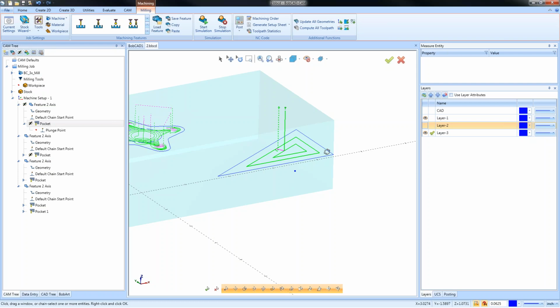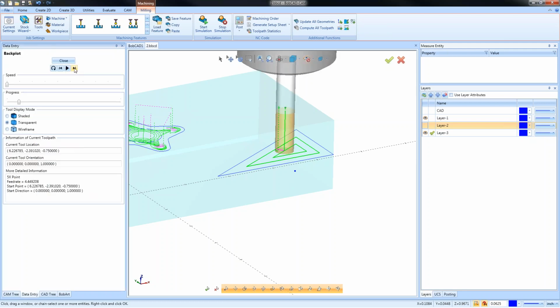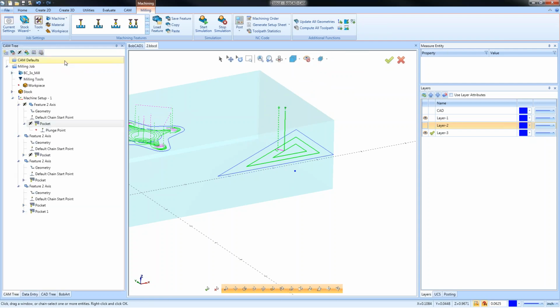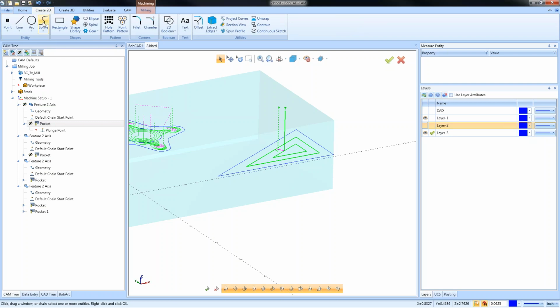All right, so what I'm trying to do here is set where the tool starts. You can see the tool picks a position now, and it starts from that position, then it works its way out. If I wanted to choose a different position because I pre-drilled a hole or something like that, I can create a point. Now, I did create this point here, but I made a mistake, so I'm just going to delete that.